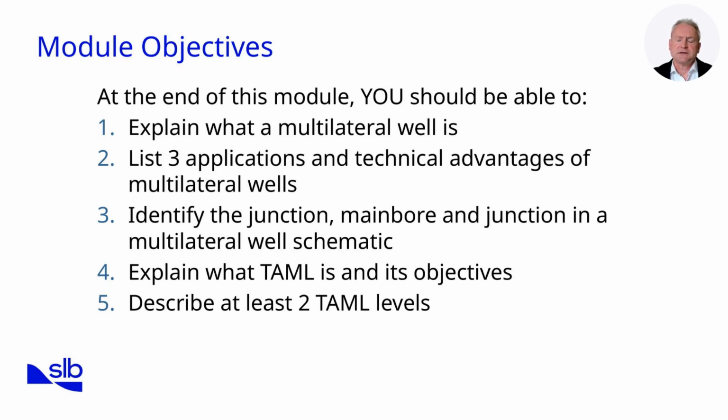design at level 6. We'll also look at summary comparisons, making it clear where each level fits in terms of accessibility, flow control, and re-entry potential. Finally, we'll review some alternative classification approaches used in the industry. By the end of this module, you'll be able to identify which TAML levels are suited for different reservoir and completion objectives and explain the trade-offs between cost, complexity, and functionality. Let's begin with Level 1.